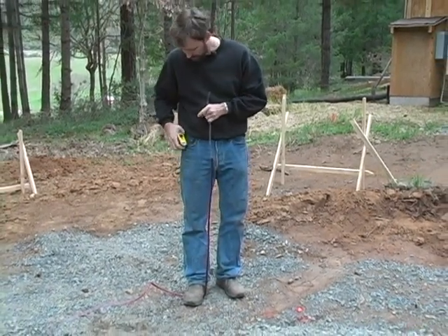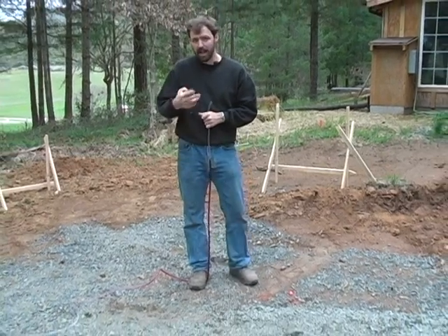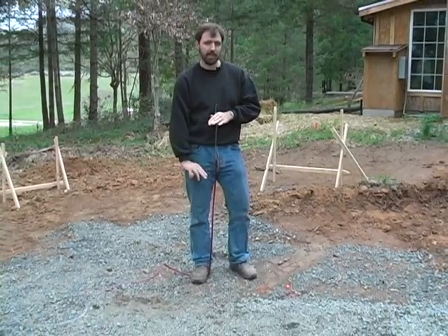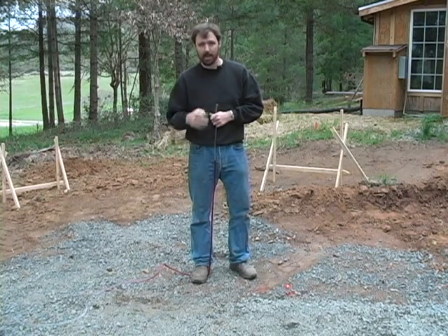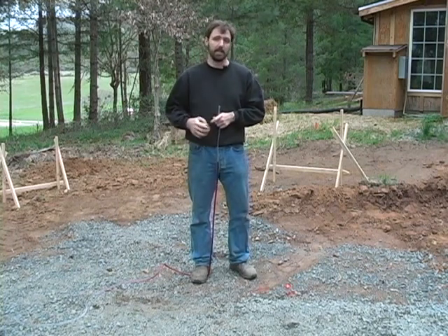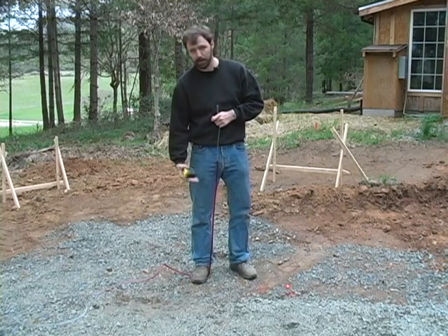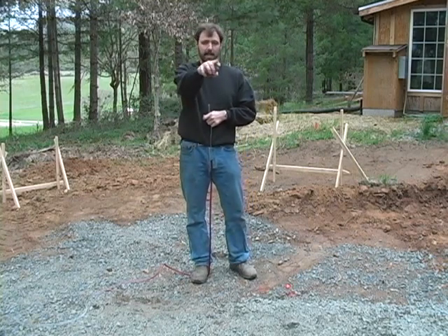I have a helper on the other side of this line in the far corner who's measuring the same over there. Now for example, if they come in at 34.5 inches, there's a half extra inch between the top of the red water line and the ground. That means that they are actually a little bit lower on that side because the number's bigger, so that they have further to go before they get to the ground. So we know that that end would be lower.